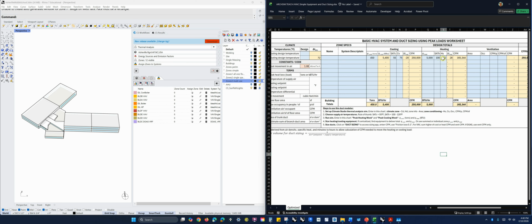So that's going to make our heating air distribution more efficient. Now, if that's confusing, just realize all we're saying is that we want to pick the largest of those two numbers, because that's going to determine how big our duct needs to be. Okay, so we're done with that. We're going to say that we need 250,000 CFM total for the project.